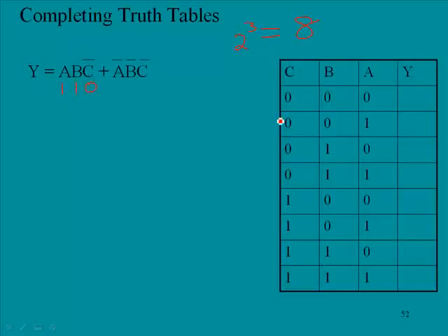It might be helpful to turn that around. If we had 0, 1, 1, that would be in the form that we have it here. So let's see, 0, 1, 1. Okay, that's the number 3. We should have a high right here. And then this is going to be 0, 0, 0. That one's pretty straightforward. We should have a high right here. Now, all of these other potential inputs will result in a 0. We will have a high at these 2 points.